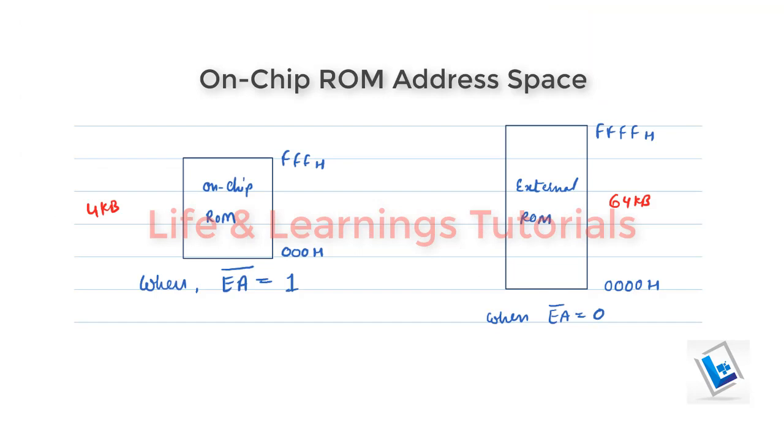Now let's move to the memory organization of 8051. If I consider the on-chip ROM or flash memory, then for standard 8051 it is only 4 kilobytes of ROM. The program counter of the 8051 is 16-bit wide. So directly it can access 64 kilobytes of on-chip ROM, but the manufacturers of controllers are not providing this much on-chip ROM in the controller.